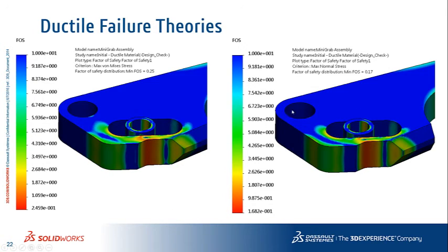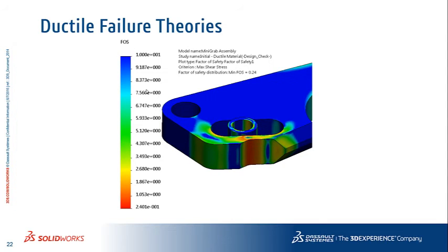And then just to summarize here, so here are the von Mises and principal stresses, and I want to point out another thing. You guys see these are basically the results that we just got, but you can see the values are very different, right? This is telling me that I've got a minimum factor of safety in the maximum normal case of 0.17. Remember, ours were about 0.7, 0.75. Here's our shear stress. Now the reason for that is because the minimum is actually occurring on this body.